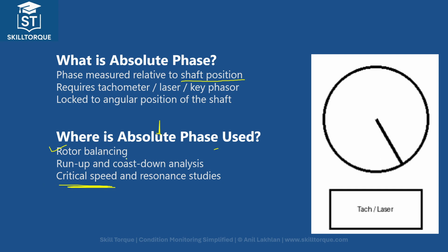In the normal route-based data collection that we do daily, vibration data collection, you will not see anyone carrying the tacho along with the sensor, right? So absolute phase is not always required for a day-to-day routine-based condition monitoring program, right?